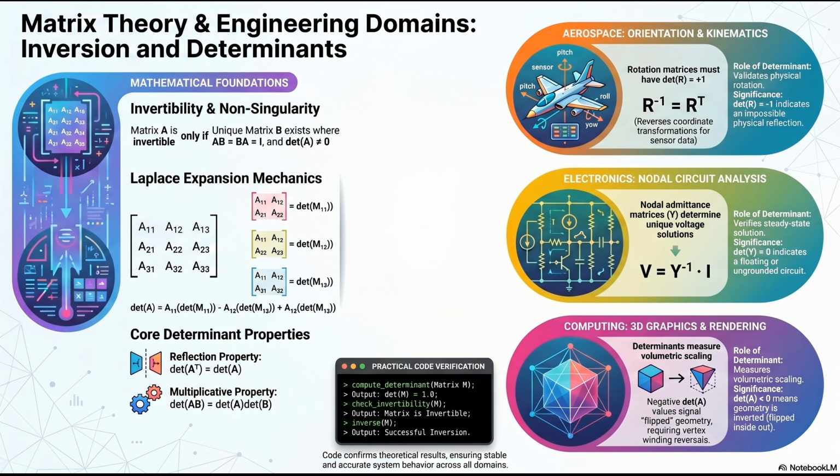Where I is the source current, the power coming in, and V represents the unknown node voltages they want to find. Right, but Y is the fascinating part here. That's the nodal admittance matrix. Y essentially represents conductivity. It maps out how easily current can flow between every single node in the network, factoring in all the resistors, the capacitors, the pathways. Here's where it gets really interesting, at least for me. Because I found myself thinking of it like a massive, complex plumbing system. The voltage, V, is the water pressure at various points. Wow. The current, I, is the actual volume of water flowing through.